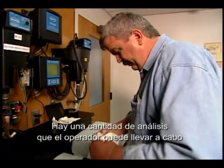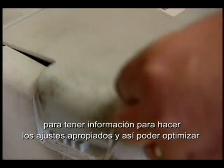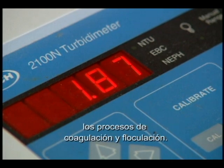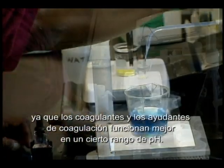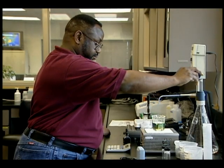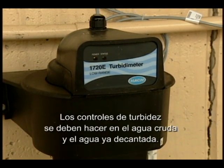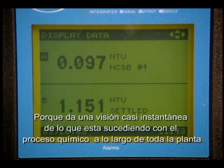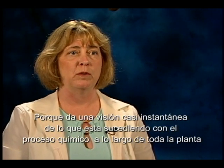There are a number of tests the operator can conduct to gain information to make the proper adjustments in optimizing the coagulation and flocculation processes. The operator can test the water's pH level, since coagulants and coagulant aids work best in a certain pH range. Turbidity tests should be performed on both the raw and settled water. That gives you an almost instantaneous view of what's happening with your chemical processes through the treatment plant.